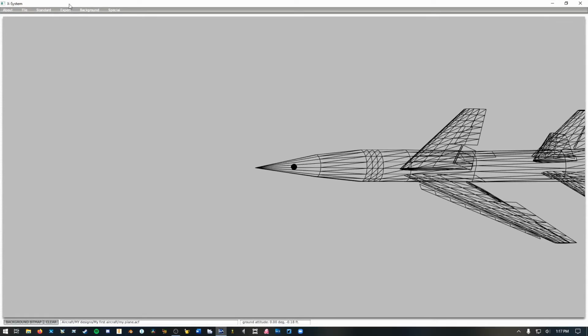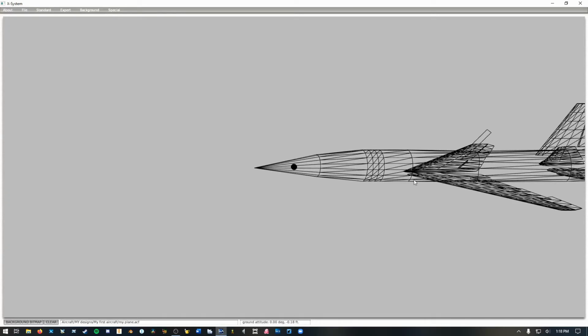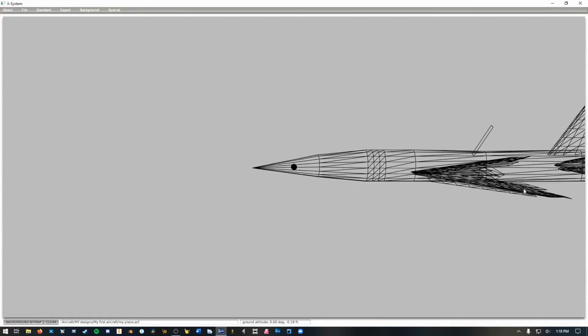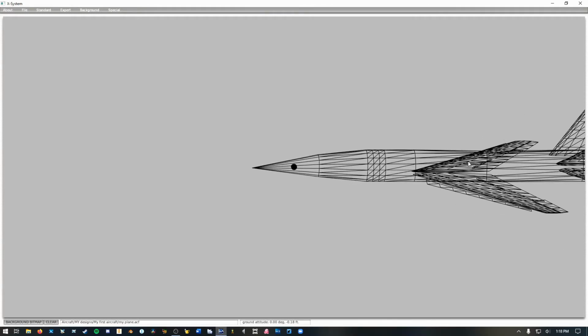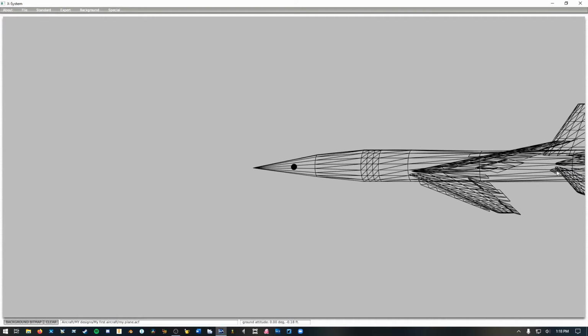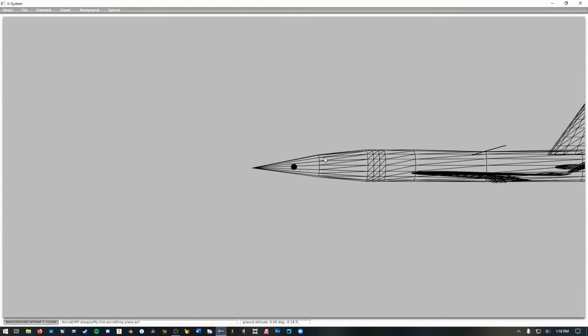And so obviously if the center of gravity of the aircraft is right here, and the center of lift of the aircraft is somewhere around here, when we try to induce a pitch moment, we're not going to really have an easy job of doing that because the center of gravity is going to be over here pulling down while we're trying to move all of this up.